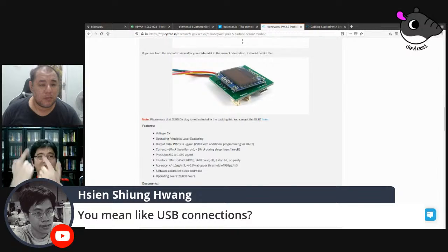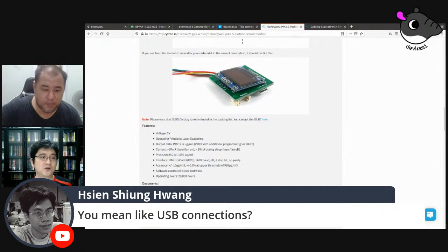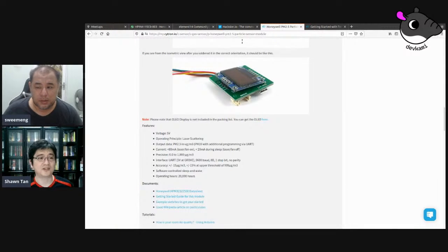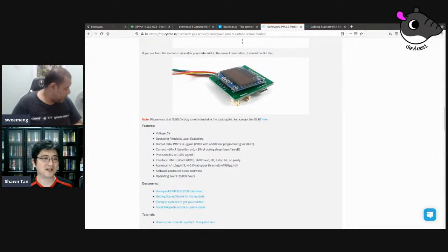You send, and then after that you listen, and then you send, and then you listen. All of the transfer happens over those two pins, and you can set them on and off according to what is needed. But of course it's limited. If you are Bitbanging, because you're doing it in software, you can't have high speed USB. We are talking about really low speed USB 1.0, like 1 megabit, and you can do that in software easily, or maybe even 12 megabits if you have a higher speed microcontroller. But if you are trying to aim for 480 megabits, then you can't do it. Yes, precisely.